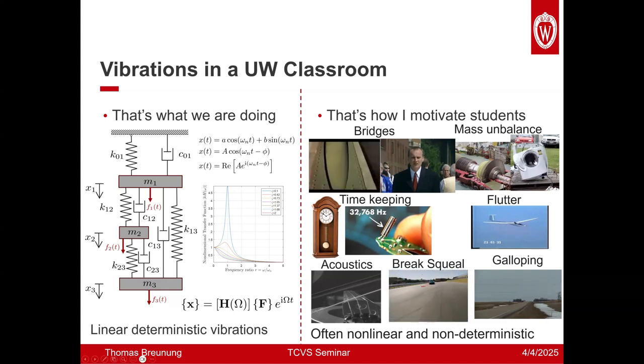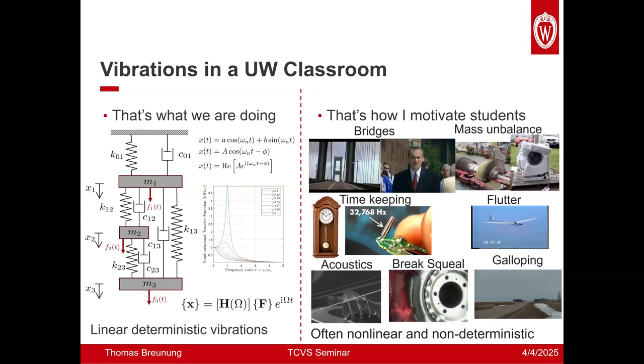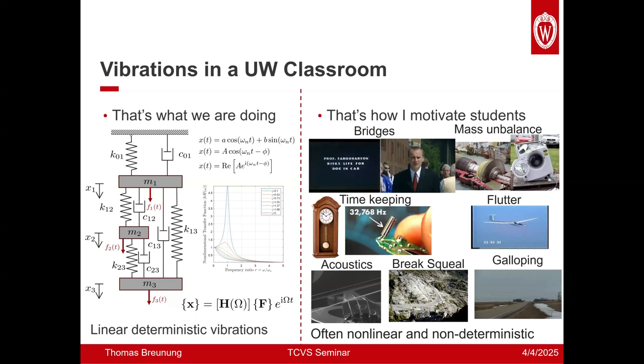Similarly, why is the laundry machine getting destroyed? Essentially what they do in the beginning is they throw in a piece of metal and then they let it run. We have continuous contact between this rattling piece and the machine, and contact is a highly nonlinear phenomenon. Similarly, with this flutter vibration or galloping, this thing is at rest in the beginning, and then certain parameters like environment and wind speed change, which gives rise to self-excited oscillations, which then go to a limit cycle.